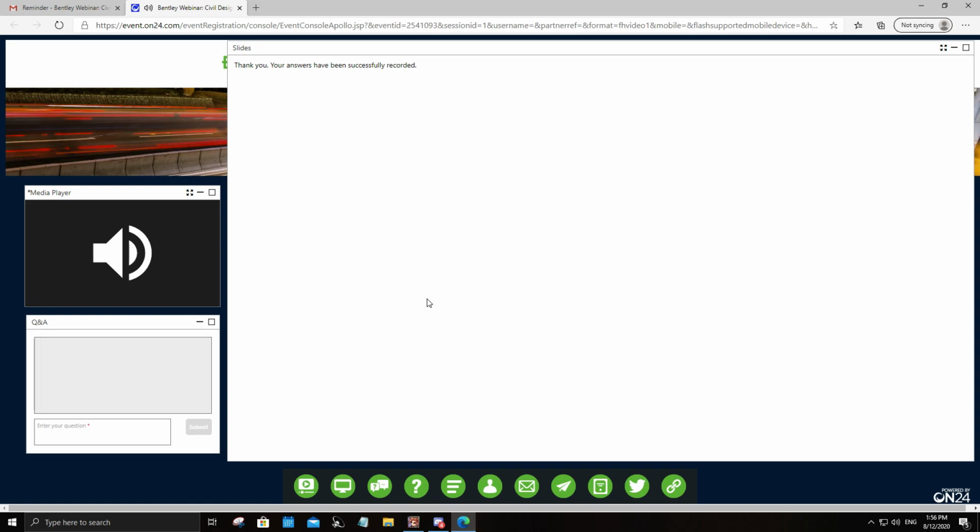So all you need to do is export your terrain or surface model to LandXML, your alignment as well to LandXML, and then from there, OpenRoads can open it and convert it into DGN. I hope that addresses the question.